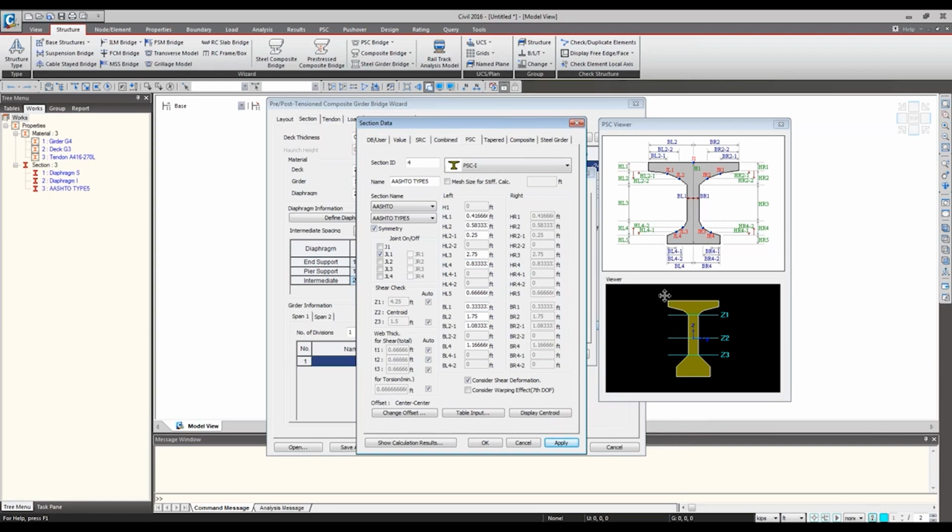If your girder has to be elongated at the flange or at the web portion, for the splice girder you will have to lengthen the girder, or above the pier, for the concrete pour, if the bottom flange needs to be thicker, you can freely modify that any way you need. So from 0.6 to 0.5, I could increase my flange thickness like this. This way you can freely manipulate the section based on the database.